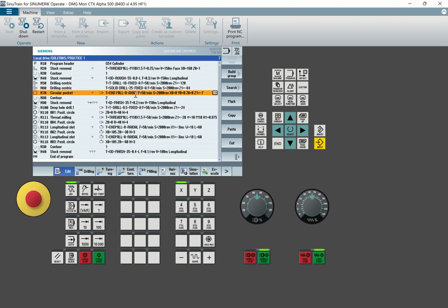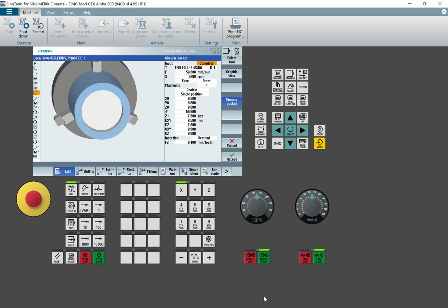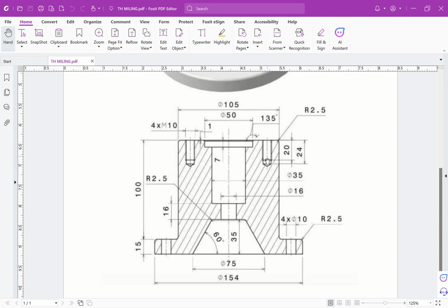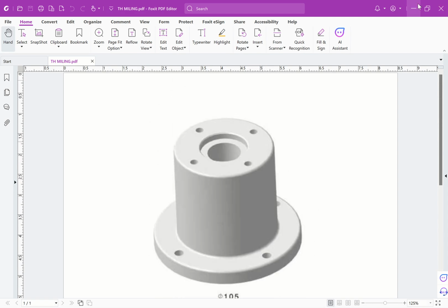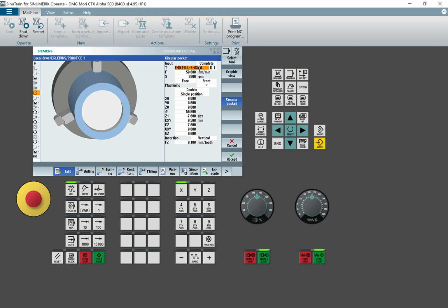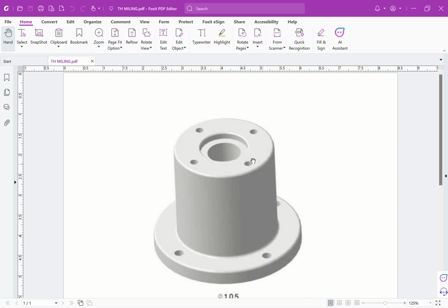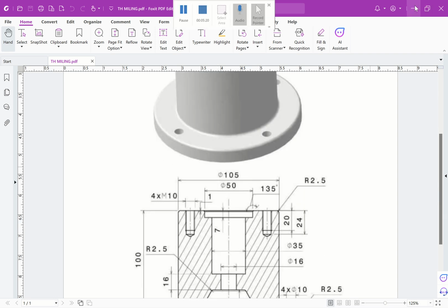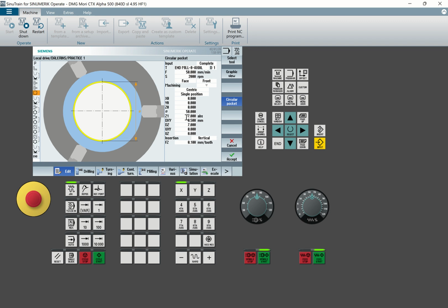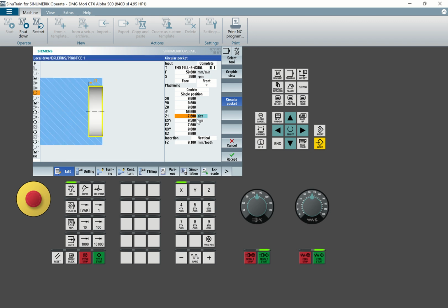And then I went to pocket on this face. As you can see from this face, I have this small pocket. This is what I did, using an end mill of diameter 8. Okay, I can use even more than 8 because the hole is bigger on the face. So I'm using on the face, not per surface. It's a single. The diameter is 50. I can show you the diameter here. This is diameter 50, and then it has this depth going inside -7. Then I'm cutting it once. Then from there I exit it.